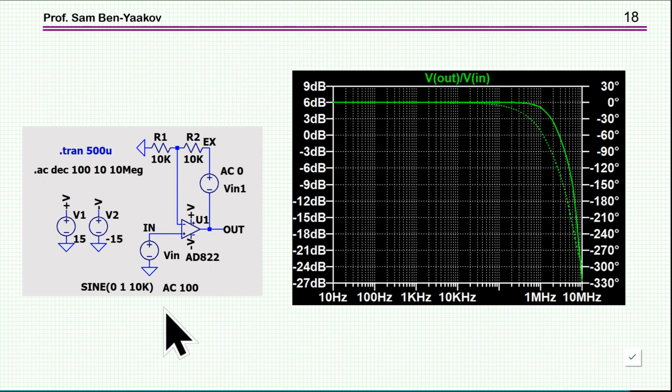Now, again, although this is an operational amplifier, if it is compatible with AC analysis, SPICE will linearize it, make out of it an equivalent circuit which is linear and therefore insensitive to the amplitude, and this is just for demonstration.